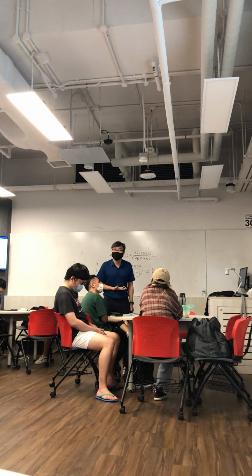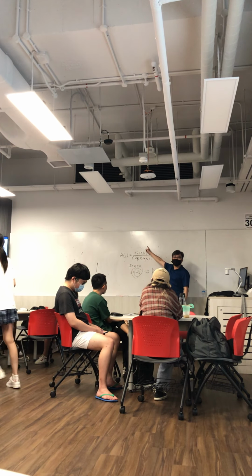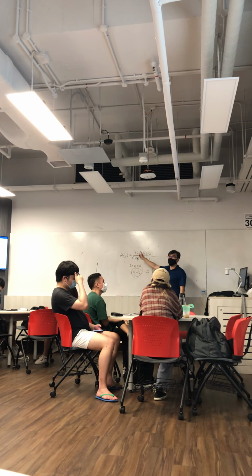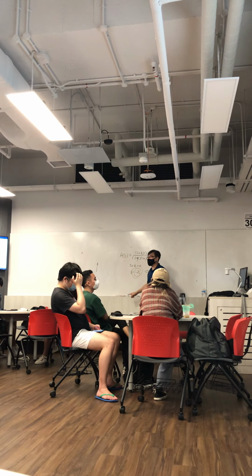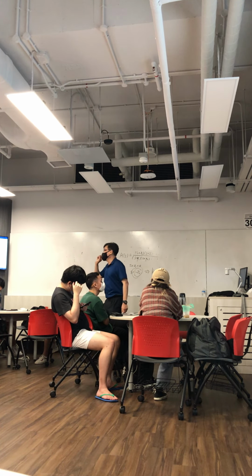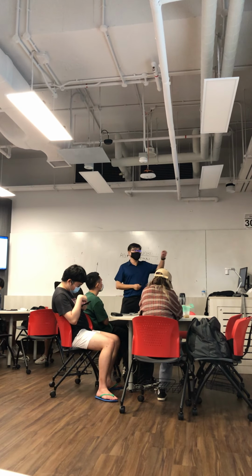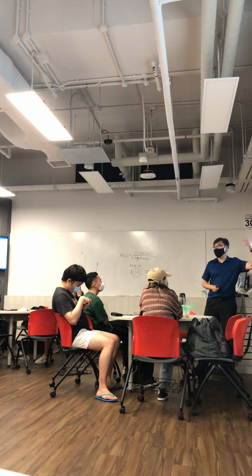So I explained why zero. Zeros appear in the numerator. You can determine zeros from the numerator. And since S is related to frequency, basically you find at what frequency the transfer function is equal to 0. The transfer function magnitude can be 0 at a certain frequency. So this is what you find.